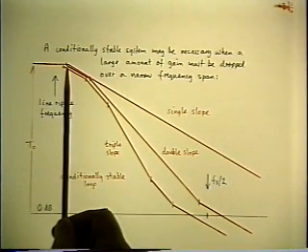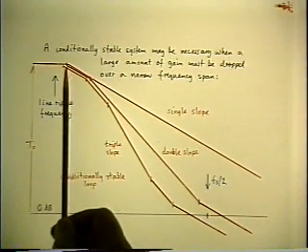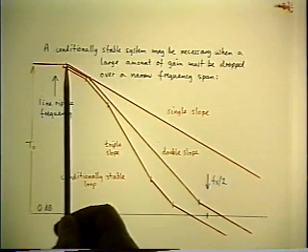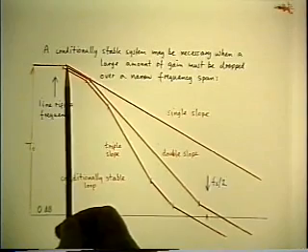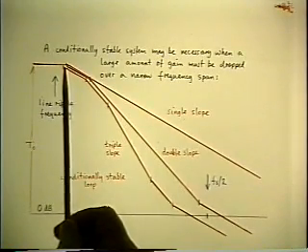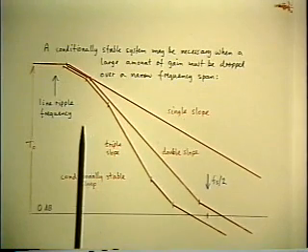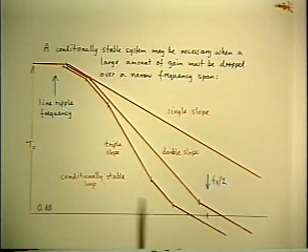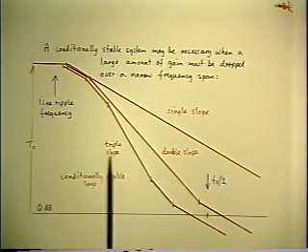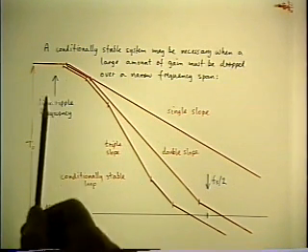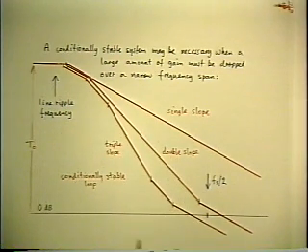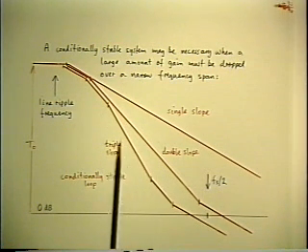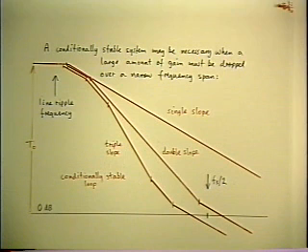Because you have other things that you can do to meet the specifications. That is, the easiest thing to do is to lower the requirement for how much loop gain you need at this frequency. If it's a matter of distortion reduction necessary to meet the specifications, then a better way to approach it is to make the output stage more linear. So you don't need as much feedback to get the same answer. And the same thing is true with other requirements as well. There are other ways in which you can reduce the stringency of the requirement, so effectively you can widen the window. And that's a better way to go around the solution than simply try to design the conditionally stable amplifier.